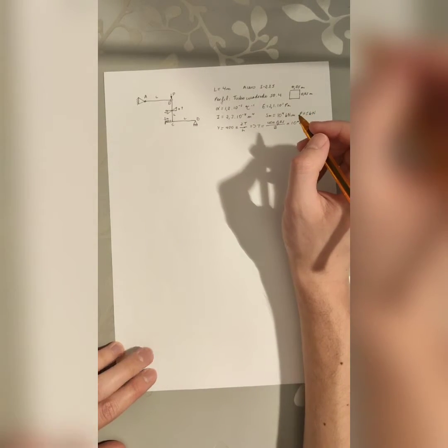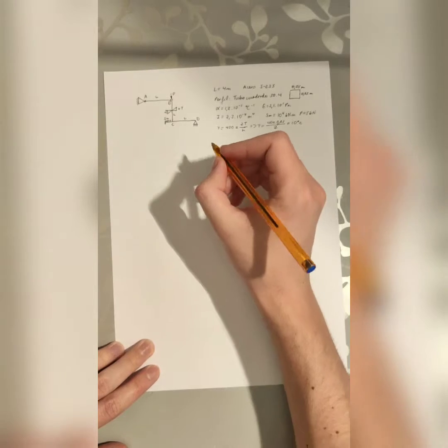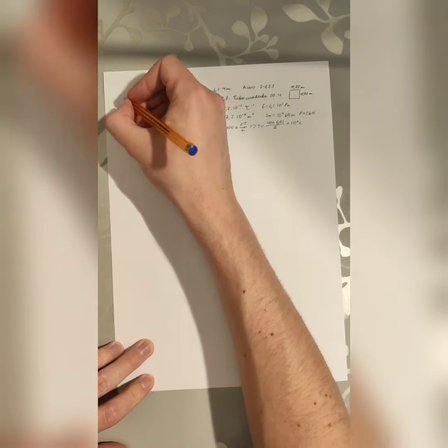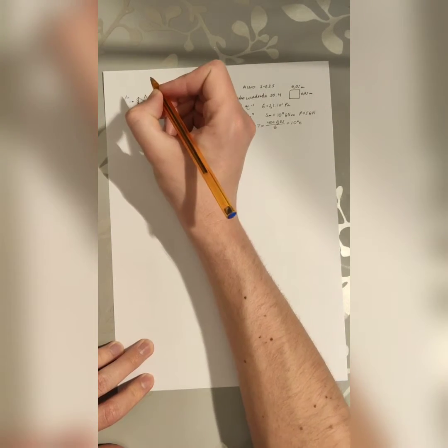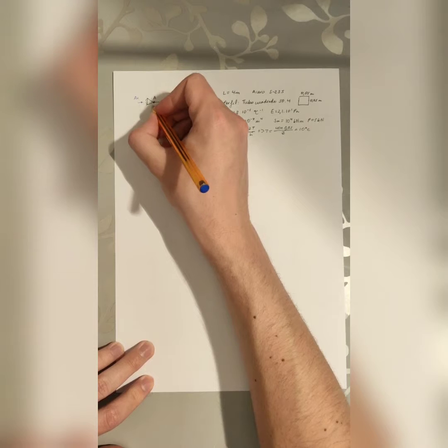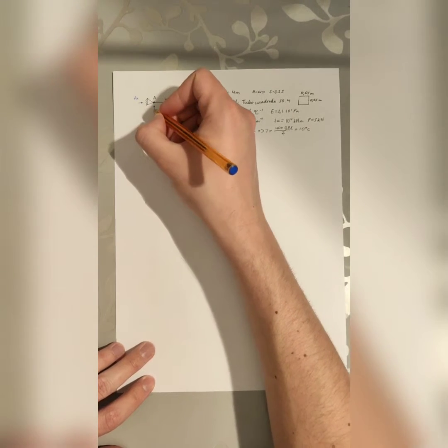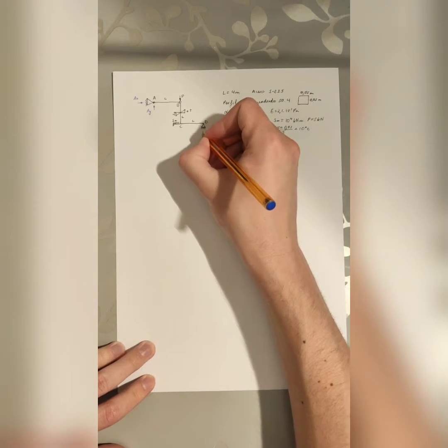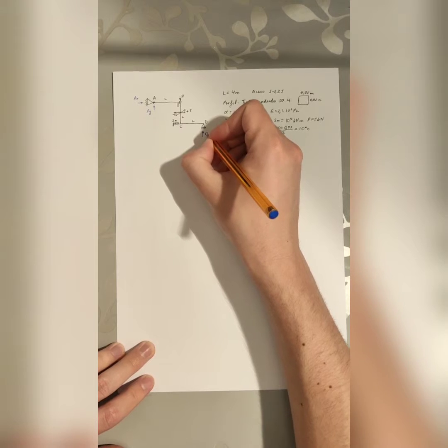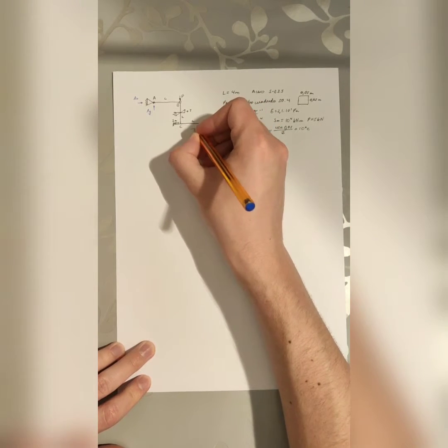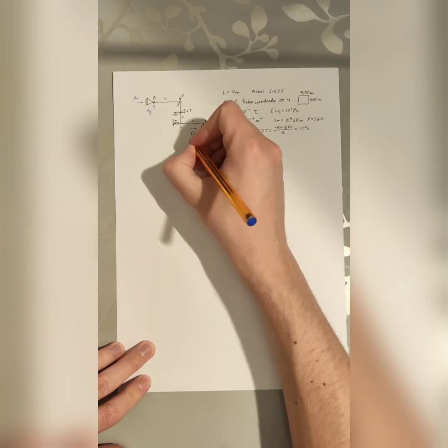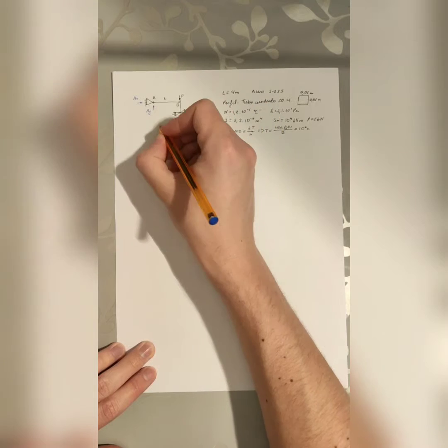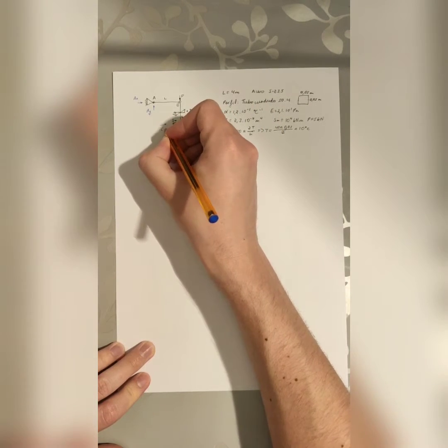Therefore, the reactions that we have are, first, a horizontal reaction at A, AX. Then a vertical reaction at A, AY. Then a vertical reaction at D, DY, and a horizontal reaction at D, DX. Lastly, we have the reaction on the spring, which is CX.